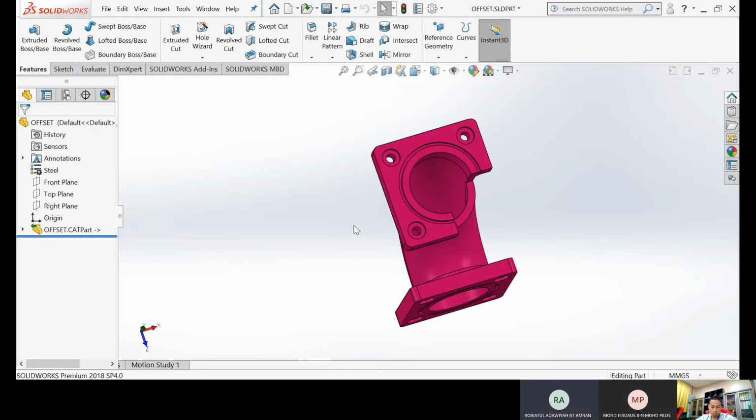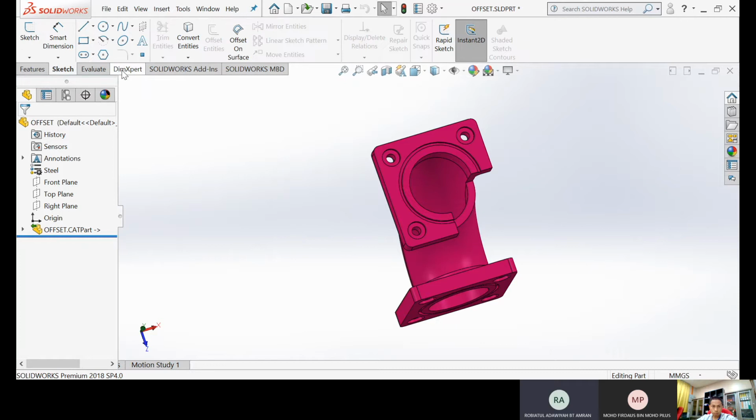Next, part 4, automatic creation. First, select automatic creation. After the patches for the STL edit are produced, there is a surface error option, which means it cannot produce a patch for that area. The feature lines can be manually modified, the preview re-updated, and moved to another position. A good resulting surface can be obtained by choosing the option to relax the feature lines. Choose add feature line from points between the points so that a new feature line can be created. It gives new areas for these patches to be built. And then go back to STL edit to remove any unnecessary information for the final result to be much better.